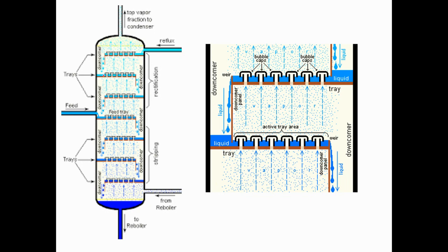Here also there are plate towers with different plates. The air and liquid droplets come out and the gas bubbles are big, due to this higher efficiency is maintained because of the highest contact time and higher contact surface. So this is how these different trays are used. This is the cross sectional view of that.